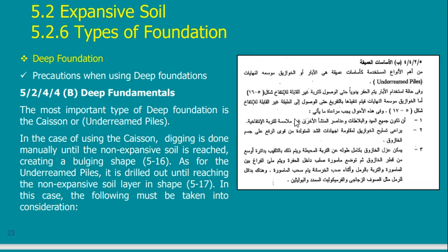It's the same original pile, but the bottom of the pile, instead of having the same cross section, in construction they make it bigger, so that if the soil wants to carry the footing up, the enlarged base of the pile prevents it from going up.